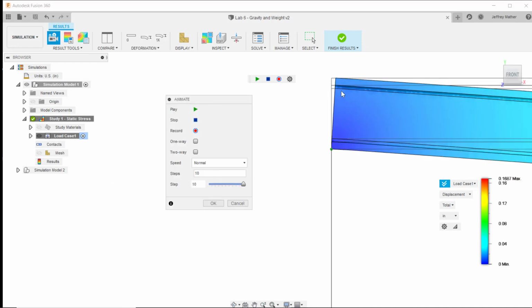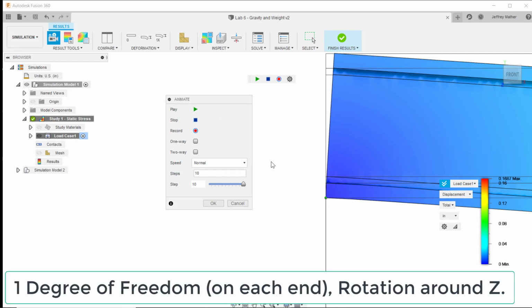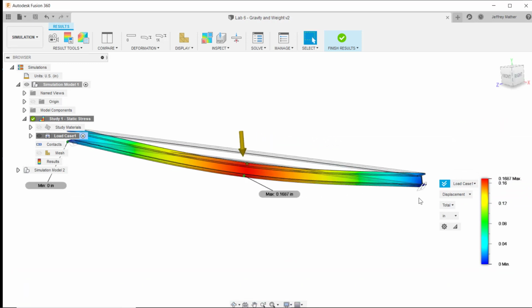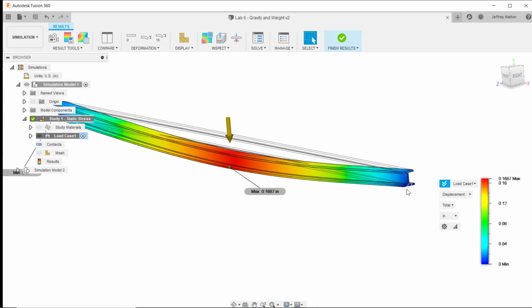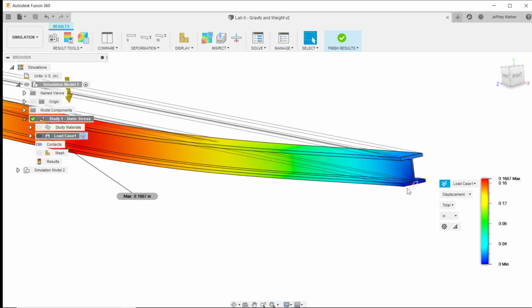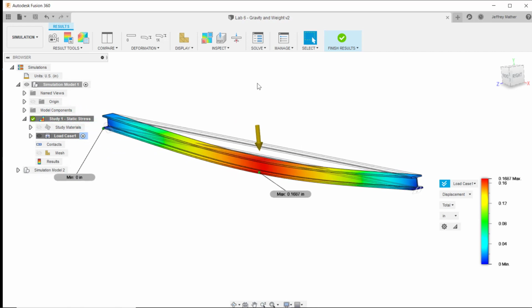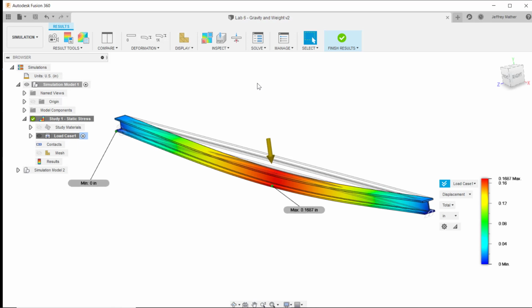Now notice here on the ends that it's rotating around this point towards the inside, and the same on the other side. In this example, we put the constraints on this very edge, but in the real world, it's not likely that we're going to have a situation where we have a beam constrained just to the edge. But that is a simplification that represents our classical hand calculation, or one method of our hand calculation. Let's look at some other results where it isn't fixed on both ends.